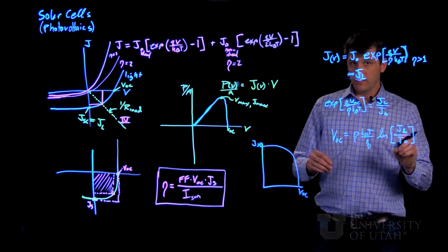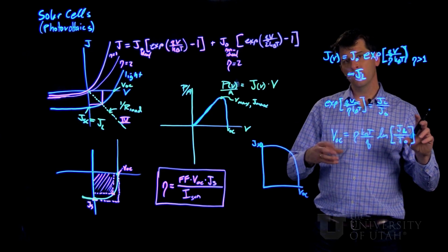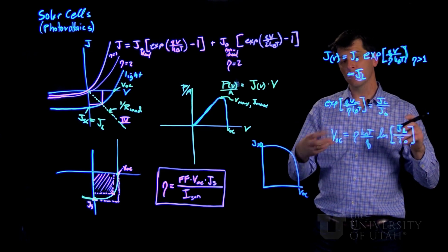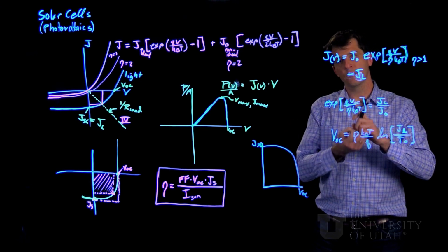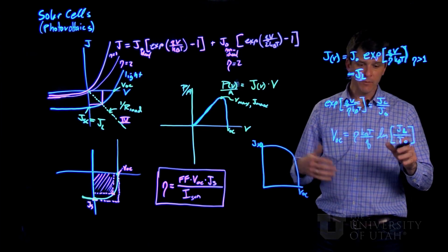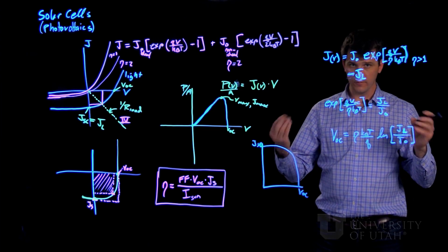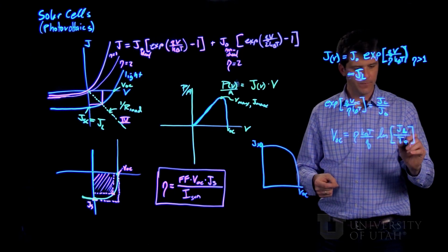However, this J naught is very sensitive to recombination, because in reverse bias or even zero bias, if you have a recombination center, it's also a generation center inside the depletion width, because the carrier densities are lower than their equilibrium values. Therefore, there will always be thermal generation.